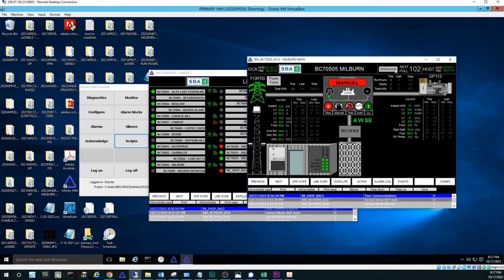We should quickly see our line voltages and frequency at normal operating levels. It is apparent that the startup has impacted the start battery values, and we can see that the oil pressure is at a normal operating value. Our instantaneous kilowatt hours and amperage do not register, as we have no load on the generator currently.